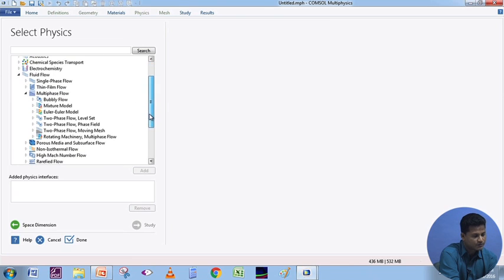When I click on this multiphase flow, I find different models present here: bubbly flow, mixture model, Euler model, two phase flow level set, phase field, moving mesh and rotating machinery, if I have a stirrer or some moving part in our geometry. The bubbly flow, mixture model and Euler model are used in those cases where we know which is our continuous phase and which is our dispersed phase. When we are certain about our continuous and dispersed phase or about what the flow pattern can be, then we choose these models.